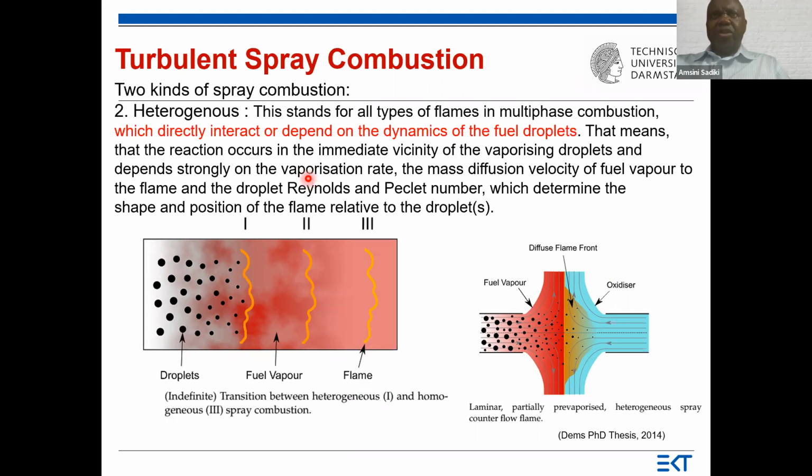In this part, the point is that if we also represent everything in this counterflow flame, we see that the droplets do not have enough time to evaporate completely, and part of the droplets enters into interaction with the flame, in the case of diffusion flame here, and it should also be diffusion. So we see that we have interaction between the flame and the particle.